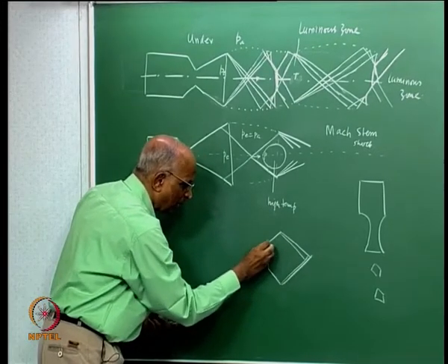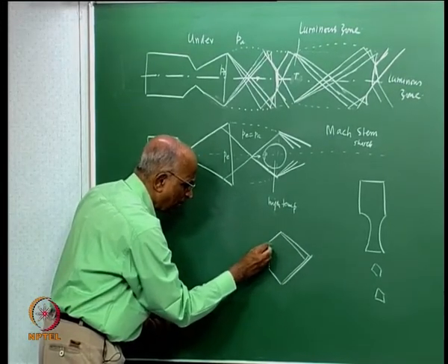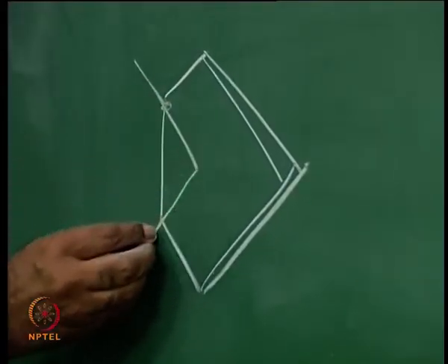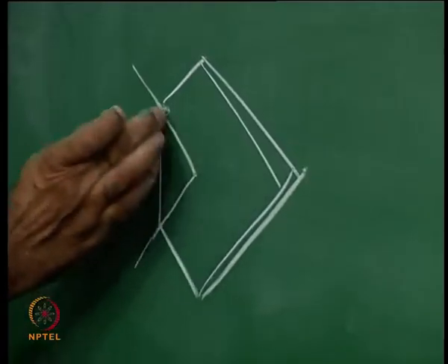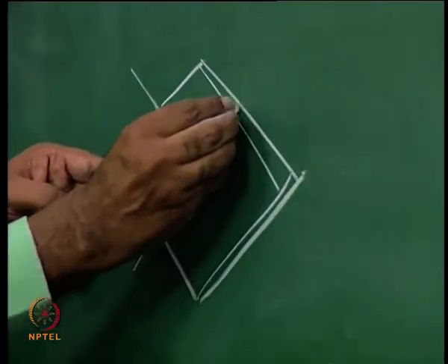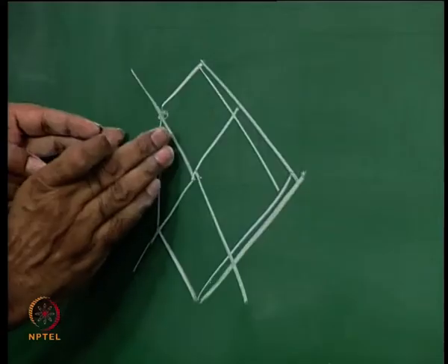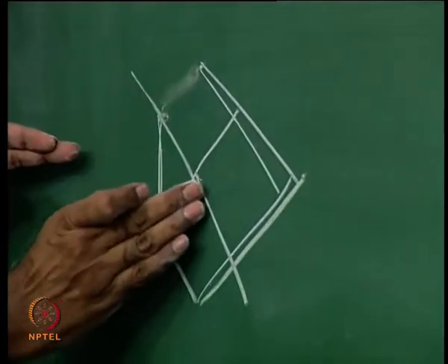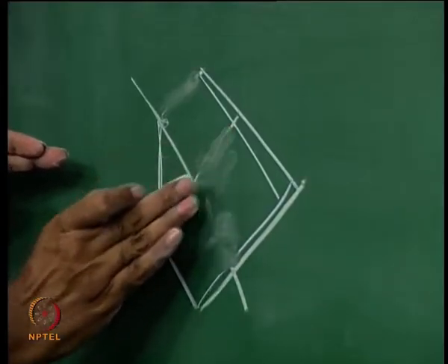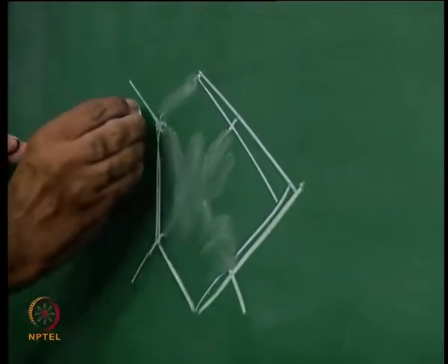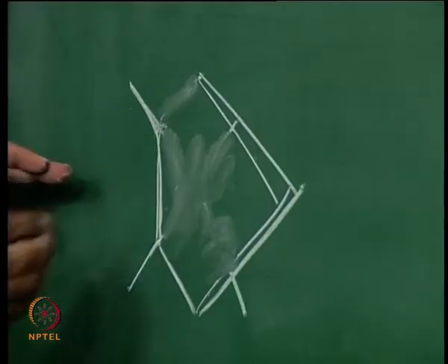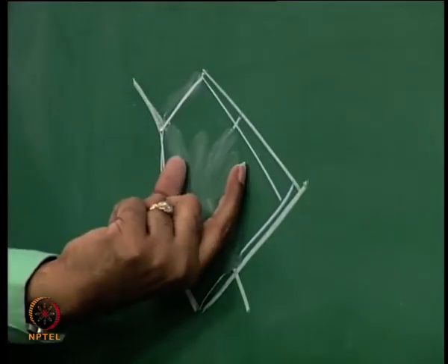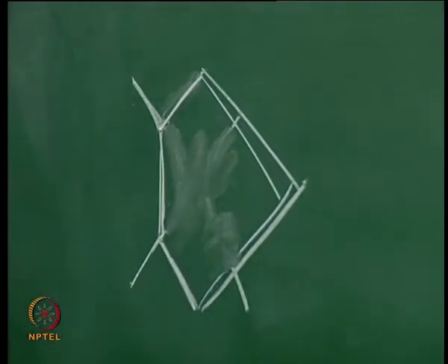Therefore, this is how the pattern looks. Normally, I would have expected maybe incident waves like this. What we said was the diamond pattern is something like this, and then you have the reflected shock which goes, but very often you have a Mach stem shock, and I do not observe this reflection pattern over here. I will have a shock like this, and then it gives rise to the reflection over here, and I get a diamond over here, and this is what is there.